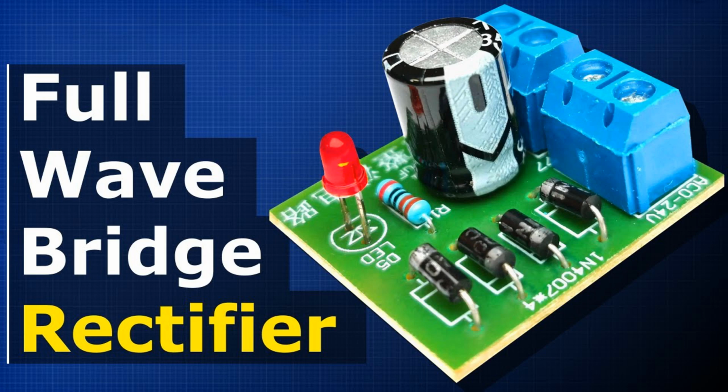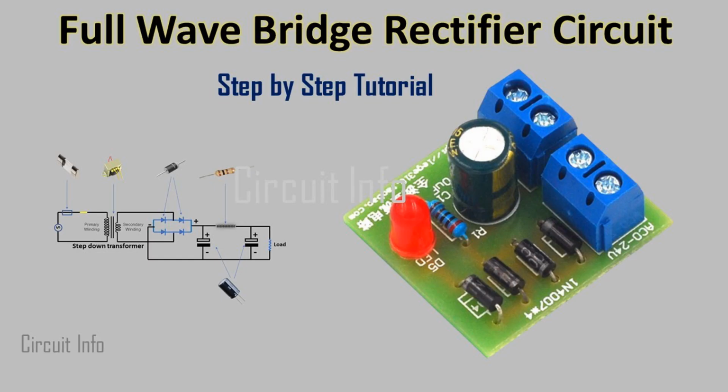Advantages of the full-wave rectifier diode circuit, bridge rectifier, over the half-wave rectifier include: higher efficiency: the full-wave rectifier utilizes both halves of the AC waveform, resulting in higher efficiency compared to the half-wave rectifier. Smoother output: since both positive and negative halves of the AC input are rectified, the output has less ripple and is smoother, requiring less filtering. Due to its efficiency and smoother output, the full-wave rectifier diode circuit is widely used in power supplies and various electronic devices where a steady DC voltage is required.